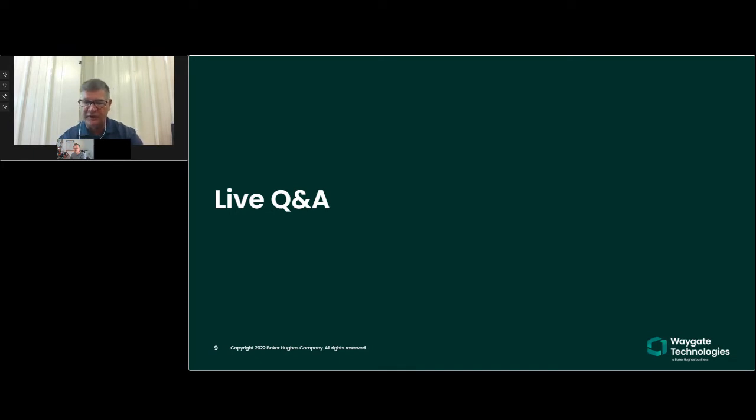One last question just popped in from Fabio. I would like to know if the AI resource can be trained to recognize damages for other turbines. Yeah, that is a great question. Absolutely. We have two still-image assisted defect recognition analytics that Mr. Danvers talked about. We have one that's a third-party AIR app that's loaded on Mentor Visual IQ, and then one for the LM2500. Those have been trained, especially the AIR, for a number of different engines.